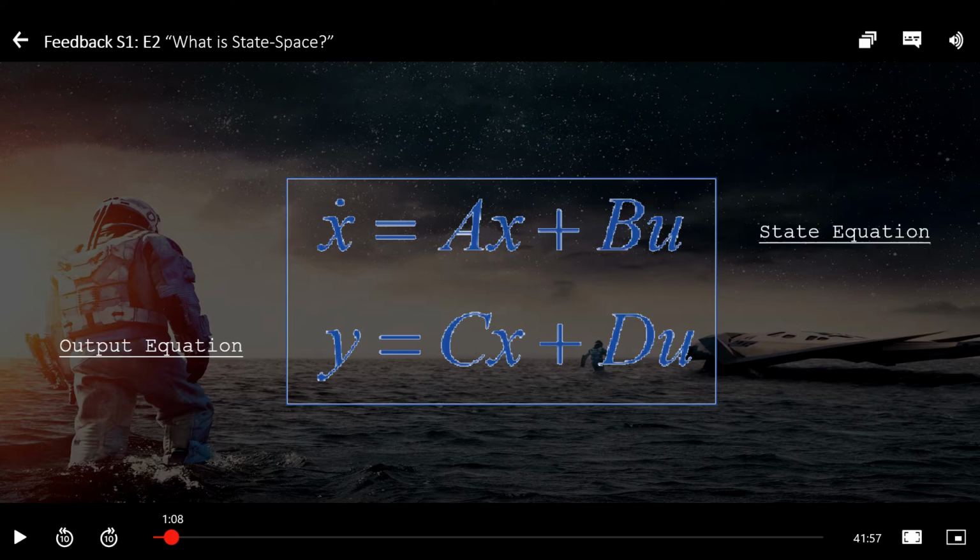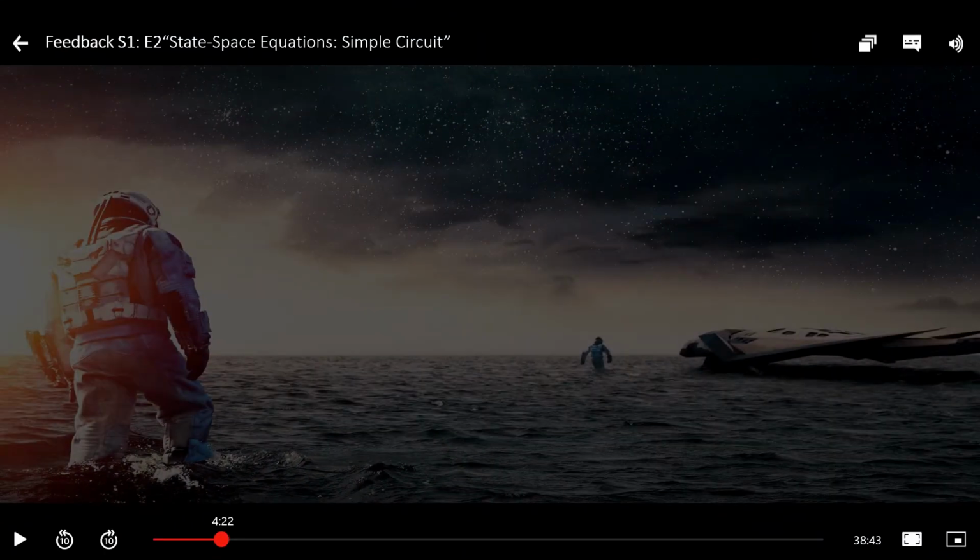In the equation, A, B, C and D are matrices. However, D is equal to 0 for most of the cases because it is the feed-through term. This model basically uses matrices and vectors to represent the system parameters and variables and evaluate the system via simple matrix algebra. Now that the basics of the modeling is discussed, we can now analyze the derived state space representations of the two RLC circuits.